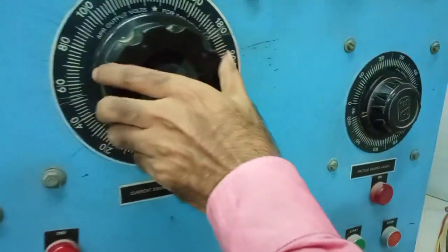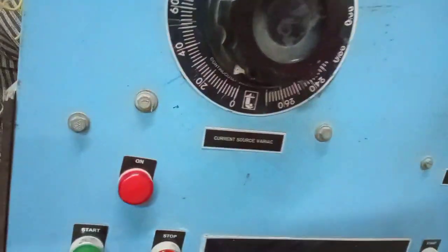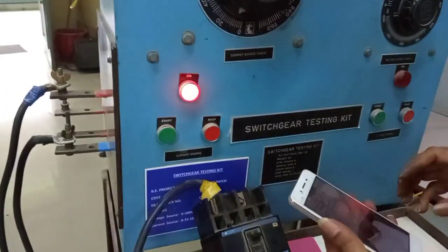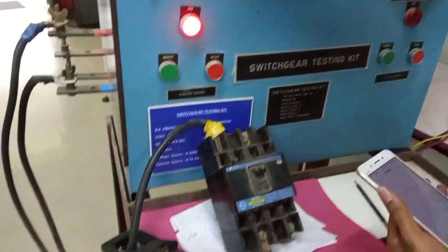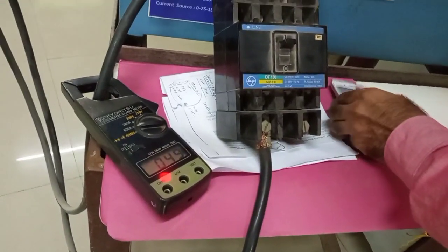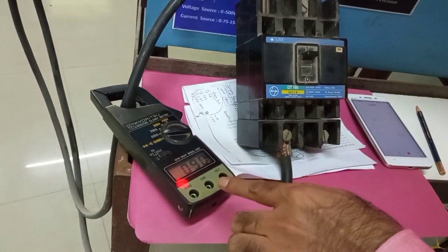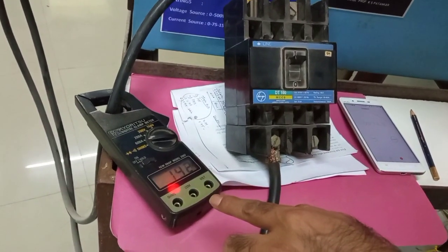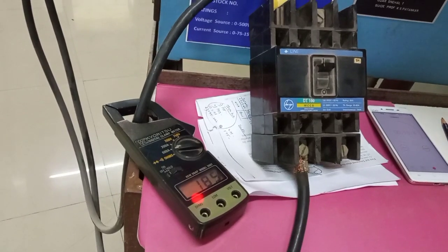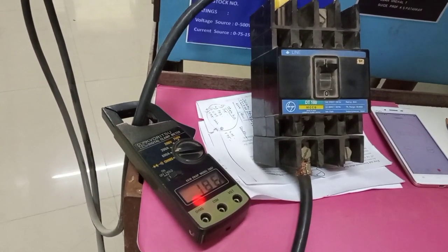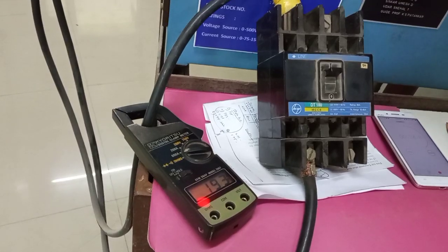Supply is switched on. So now I will switch on the MC start push button. So start push button is switched on, and at the same time the start push button is switched on, I have started the timer, and now I will inject the current. So how much current we have to inject? We have to inject 200 ampere current. So here you can see in the tester the current which we have to inject is 200. Now it is 170, 140, 160, 200. Okay, so 200 ampere current I have passed. It is 200.